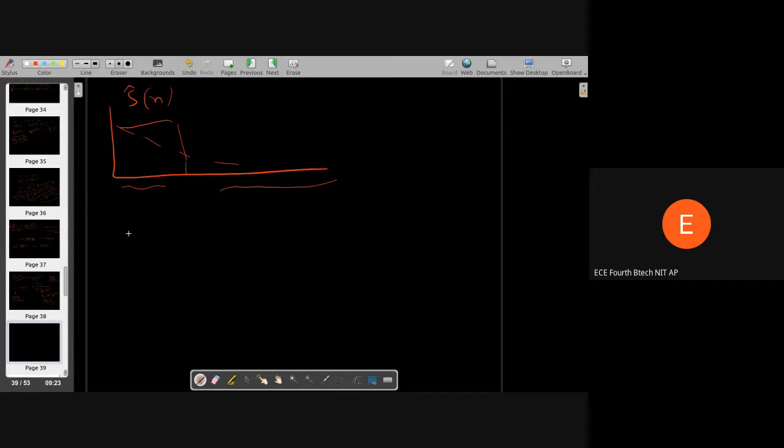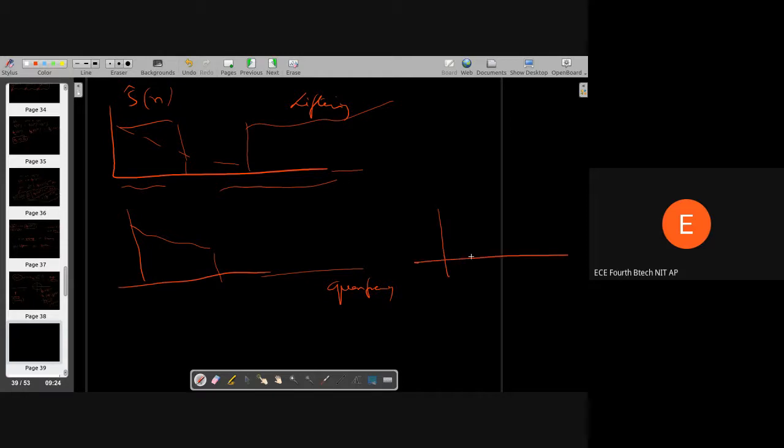You select some of the components and put the rest of them as zeros. This is most probably called low time liftering, because you have selected only the first few components of this Cepstrum. On the other hand, you can put another window, something like this, only picking the higher indices. So you will get, these are all zeros, something like this. Low time liftering, high time liftering.